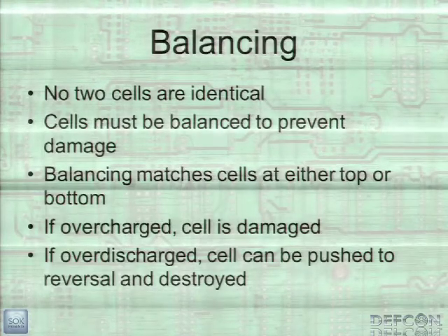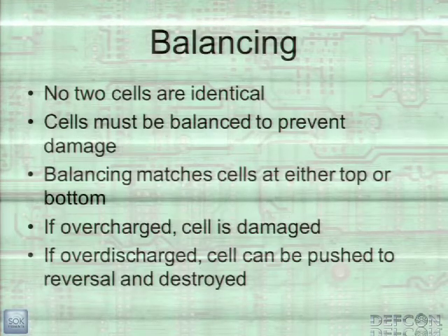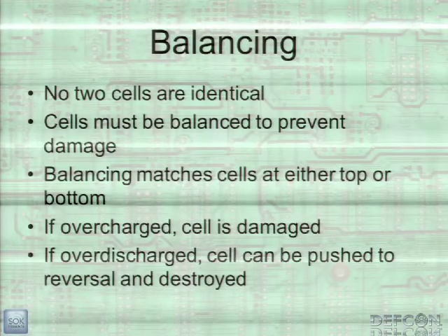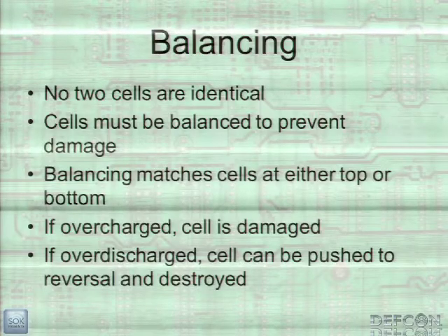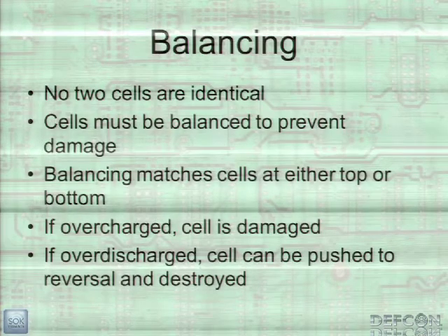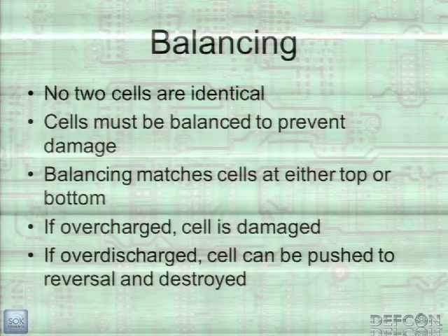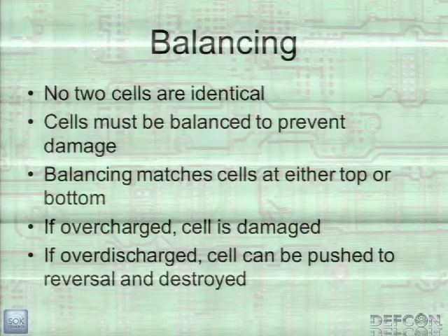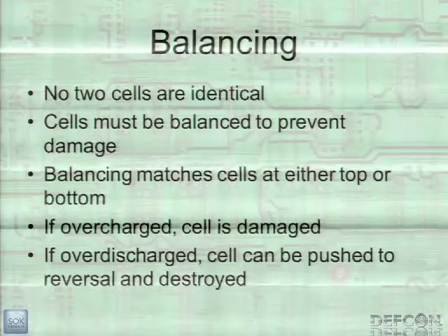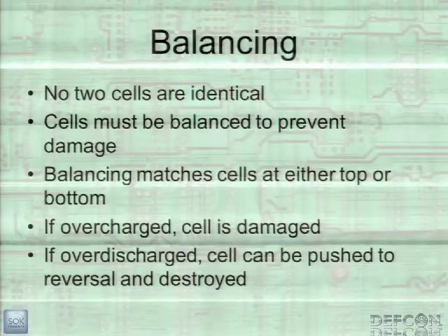Because the charge curve is so flat, you have to do it at either the top or the bottom. And by matching them all the same, you can make it so you can really charge your pack to near capacity without damaging anything. One really easy way to stay safe is to just stay away from the ends. If you don't charge it up to 100% and don't discharge it down to 0%, then you're pretty safe. If you're trying to push the limits and get the max you can out of it, then you're in the danger zone and you might hurt your cells.